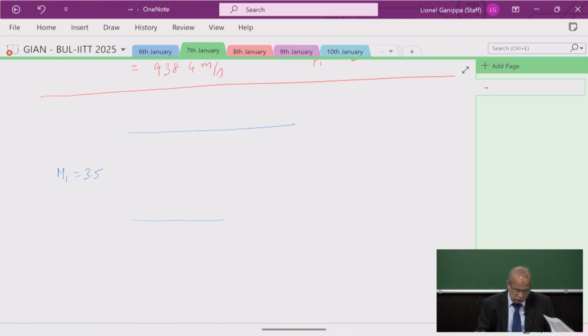Let's say that the lower wall abruptly turns the flow into a turning angle of 20 degrees. Now I don't know whether the parameters are matched, but anyhow, we'll try. Let's understand the principle of it. The flow is abruptly turned by an angle of 20 degrees. The lower wall abruptly turns. Determine the wave angle of the initial oblique shock.